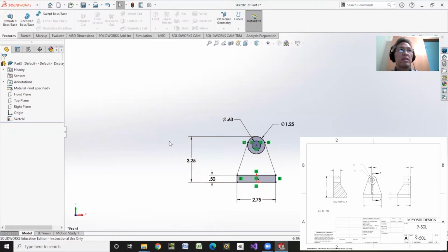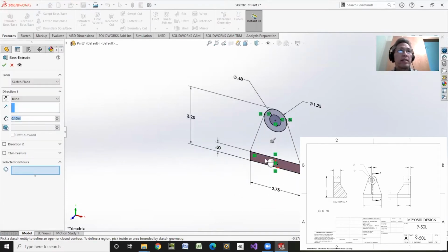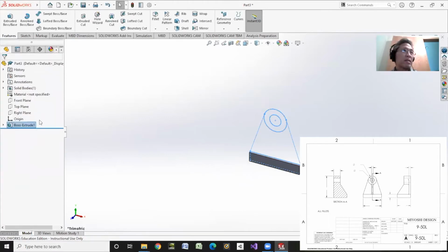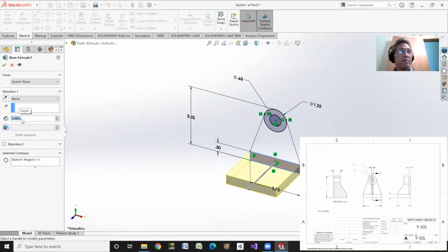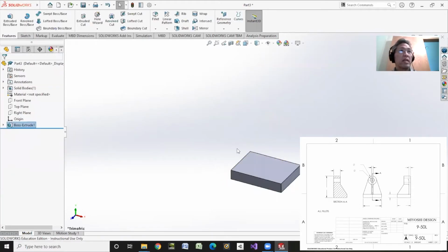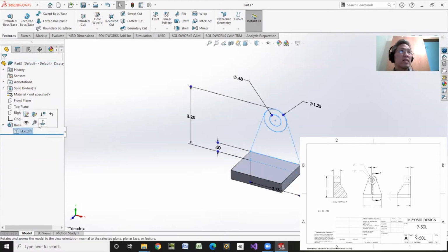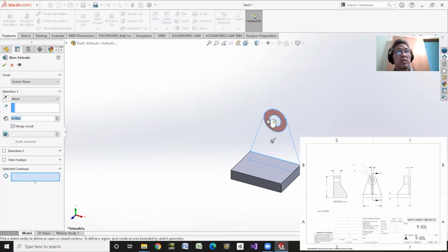And I like this feature. It's actually this feature my student taught me. Extrude boss base. I learned lots from my students. I'm going to go ahead and extrude just this contour. And I'll extrude that. Pardon me. I'll do, oopsie, what happened? Well, let's just edit the feature. Oh, that's why I didn't even change it. So maybe that's too big. Extrude that. Okay, hit the triangle here, click on the sketch, extrude boss base, and I'll extrude this guy.